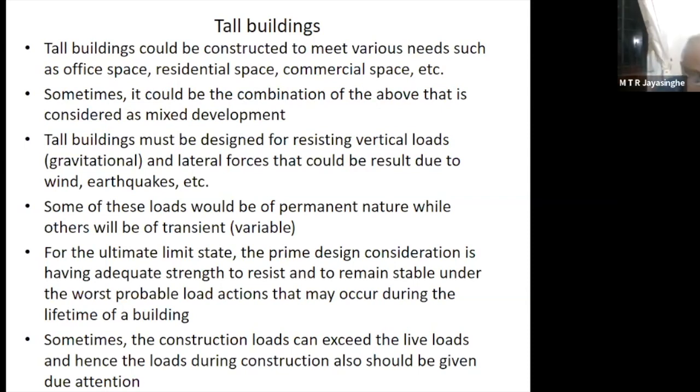The moment you keep this in mind, your designs will become very safe designs while they are economical, because you are removing all the steel from places where failure cannot occur, and you are adding some steel at places where failure can occur. For example, if I am designing a two-way slab, I will minimize the reinforcement everywhere except one place, and that place is the short span direction in the span.